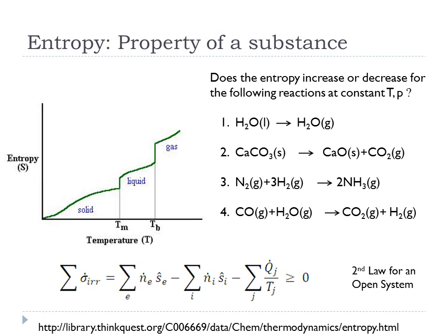But in this case, if we go above that temperature, it's not going to happen. So we actually need to stay below the temperature. And because we need to be below the temperature for any finite rate, for this to happen in a finite amount of time, we'll find we're going to be generating some entropy, as long as we are below the temperature at which, if you were to solve this equation, sigma dot would be equal to 0.